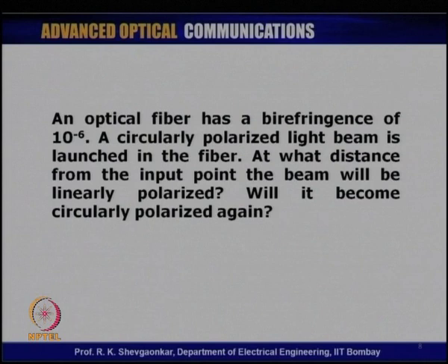Let us look at this problem on birefringence on optical fiber. As we know, since the optical fiber is not absolutely circularly symmetric, the two orthogonal polarizations propagate with different propagation constants on the optical fiber, and because of this the two polarizations undergo different phase change.